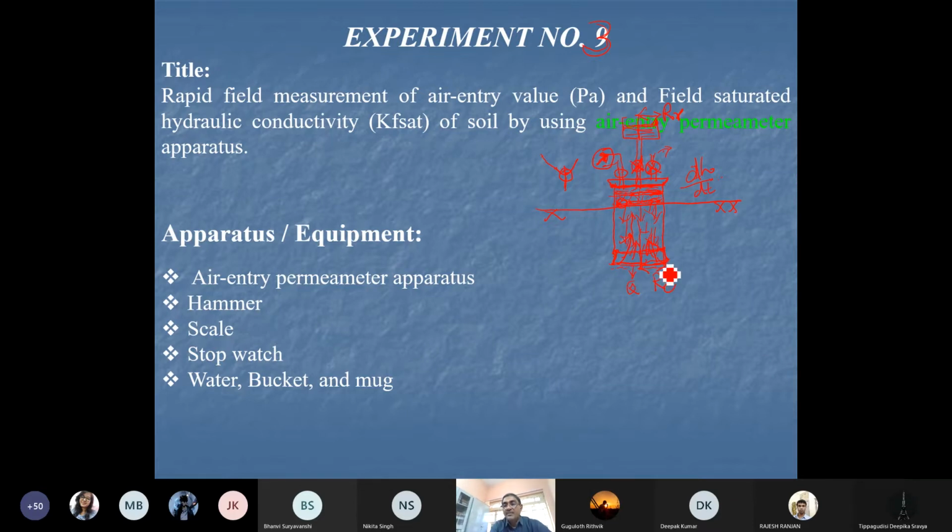Basically, this minimum suction condition is what we are assuming is the suction pressure or pressure head at the bottom of this front, exactly below the water front. That is negative, that is suction, not atmospheric pressure. However, this air bubble is moving, which creates the lowest suction at the top of the soil surface. It is not an accurate measurement of the hydraulic head at the bottom of this front.